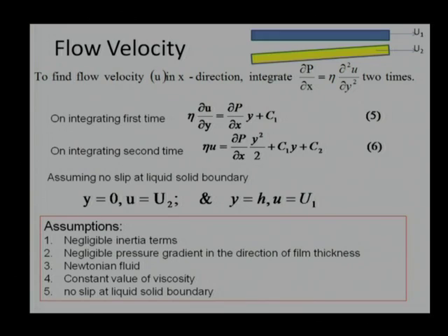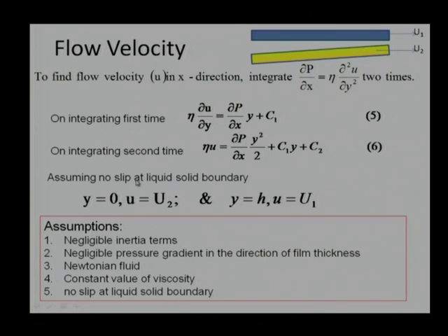If we use some kind of slip condition, then the expression will change. For most liquid cases this assumption is justified, but this will be a problem particularly in gaseous lubrication. In gaseous lubrication there will be some slippage which needs to be considered. Many times we say first order slip, second order slip, that can be considered when we develop this equation for air bearings or gas bearings.